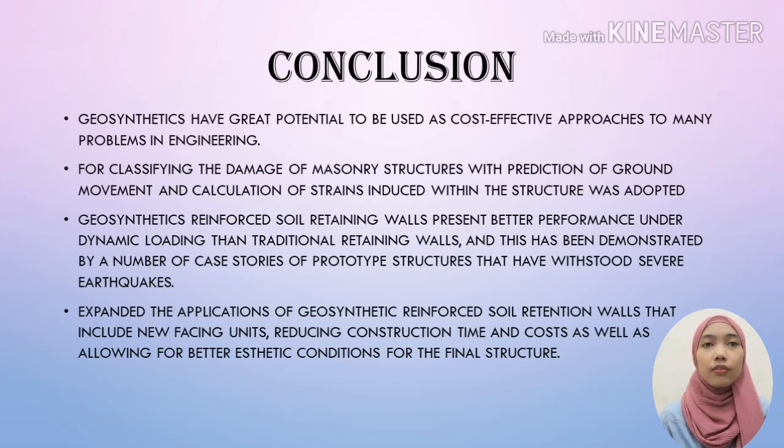And the geosynthetic reinforced soil retaining walls present better performance under dynamic loading than traditional retaining walls. This has been demonstrated by a number of case stories using prototype structures that have withstood severe earthquakes. The new construction of reinforced soil retaining walls that include new facing units reduces the construction time and cost, as well as allowing for better aesthetic condition for the final structure.